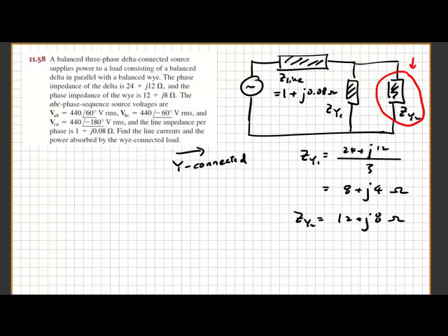So unlike the exam questions that were asked before, where you were given the receiving end voltage, in this case it is the other way around. So you know that the sending end voltage would be this. This is the sending end voltage. This is a line voltage, not line to neutral. So you will have to convert that information from line to line to line to neutral. So this is a phase voltage.